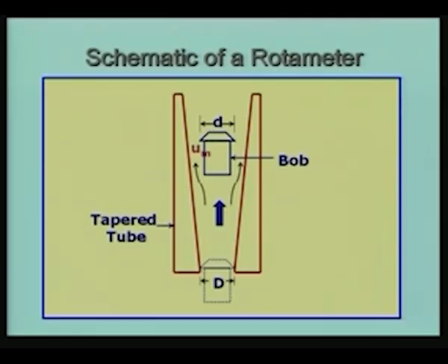In the case of the three measuring meters which we talked about, the venturi, the nozzle and the orifice plate, normally we use the horizontal orientation. The meter will be located horizontally in the pipeline, and many times the pipeline is actually horizontal, and therefore it does not involve any problem.